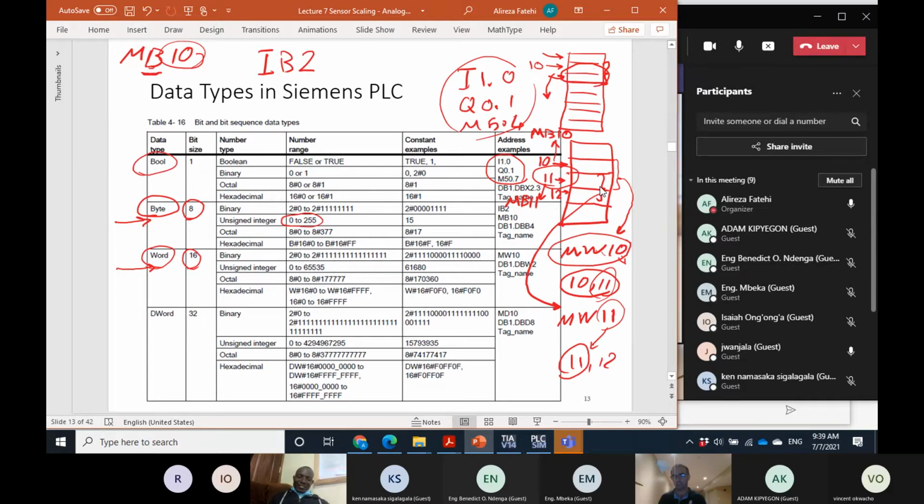And this is confusing, because maybe you change the value of MW10 by assigning some number to it. Then not only byte number 10 but also byte number 11 changes. Later, when you are working with MW11, you don't expect that the value of byte 11 has changed, but it has. It is because of this.